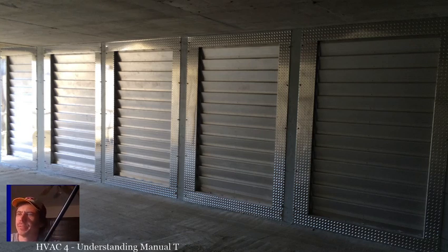Like I said, sequence of operation is the most important thing. So if you ever have to troubleshoot one, just try and look at the sequence. Most of them these days have flashing lights that tell you what goes wrong anyway, and that'll usually point you in the right direction. Basically, that light just flashes based on where the sequence messed up, and that tells you where to look. Rooftop units are pretty much the same sequence as even residential. It's really simple.